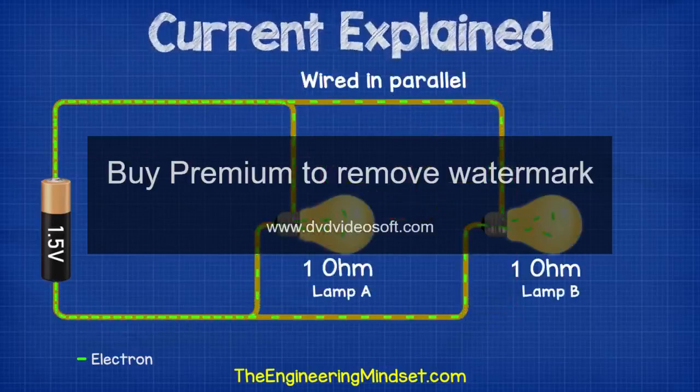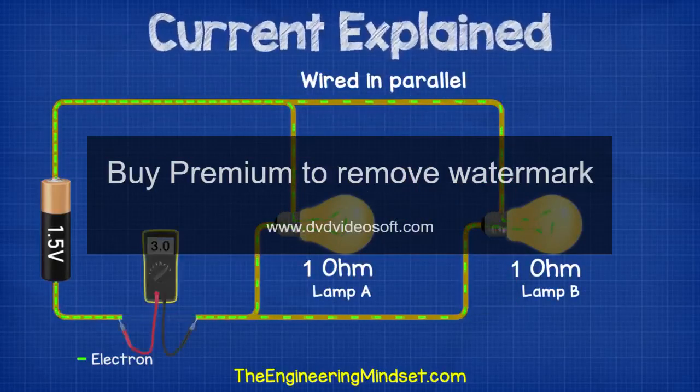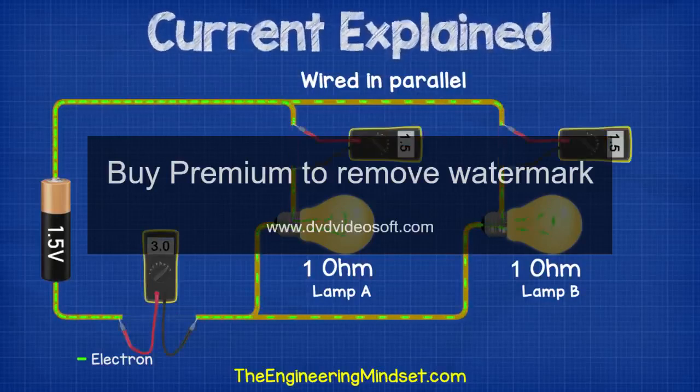If we now connect the circuit with 2 lamps in parallel, both with a resistance of 1 ohm, and connect this to a battery of 1.5 volts, then in the main wire, to and from the battery, we get 3 amps. But on the branch of each lamp, we get 1.5 amps. That's because the path of the electrons has split, so the electrons are shared with some flowing through lamp A and some flowing through lamp B. In this example, both lamps have an equal resistance, so the current is split equally.